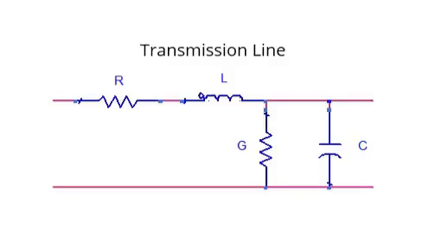All this is a simple transmission line model, right? Which is given by a resistor and inductor in series, and then the conductance and the capacitor in parallel. Right? This is how electrically a transmission line can be represented.